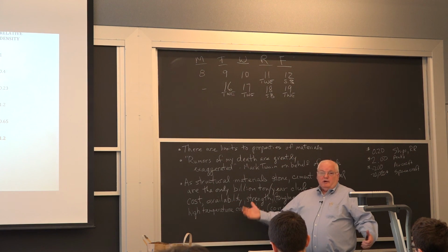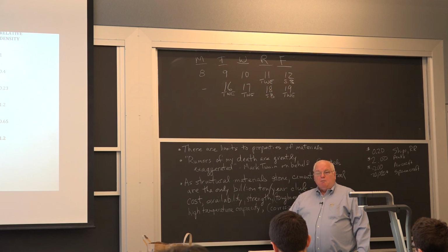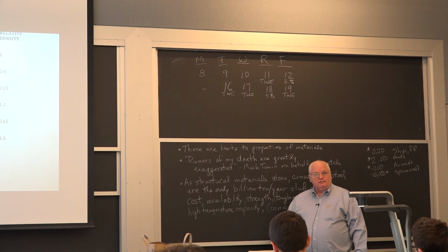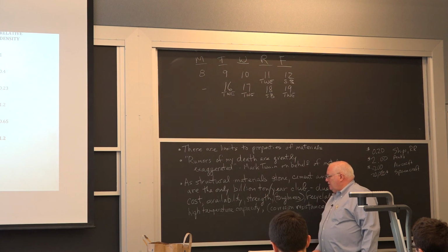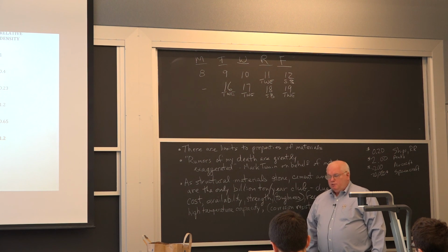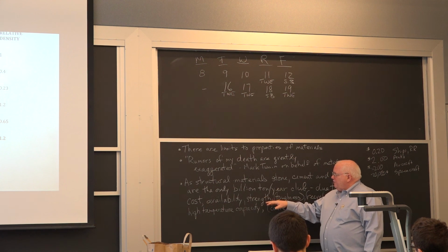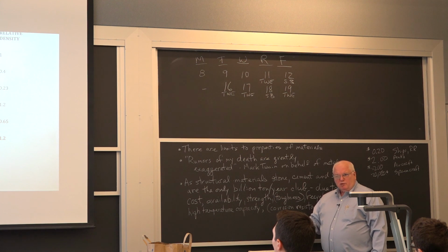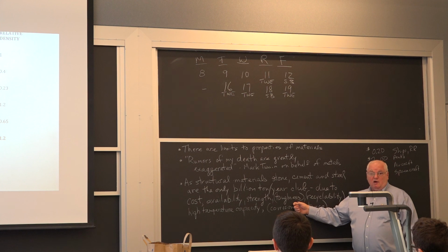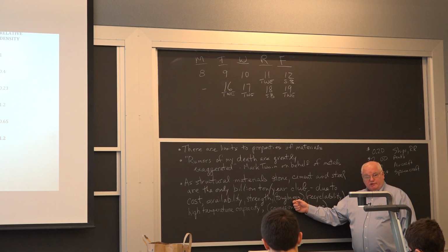Availability, well, platinum is a wonderful high temperature material, but the cost is not so great and the availability is not so great, and those two are related. Strength, we're going to talk about strength, but we have the Ashby plots, and strength can be all over the place. Portland cement's not that strong, but it's cheap enough. Toughness, well, the metals win here. This is why metals are important, because of toughness. Portland cement's not very fracture resistant.